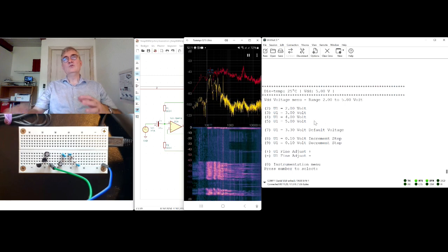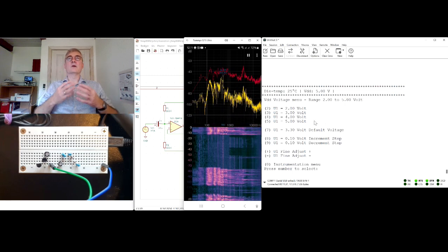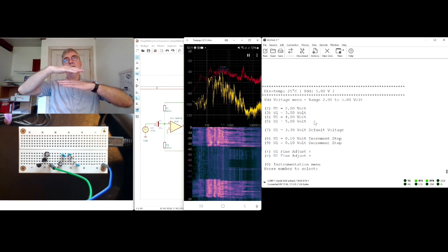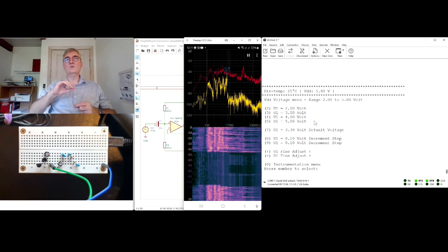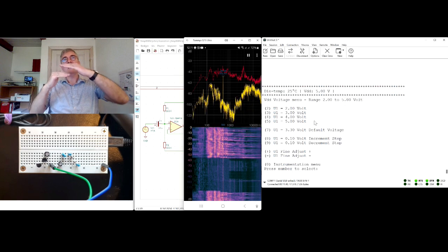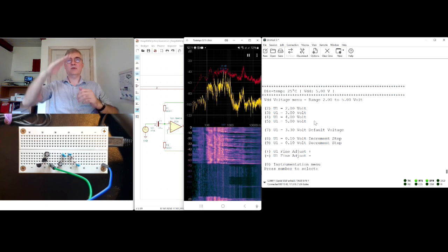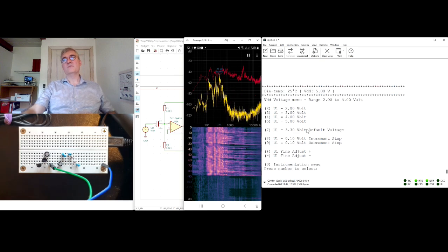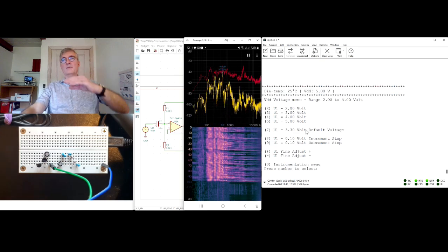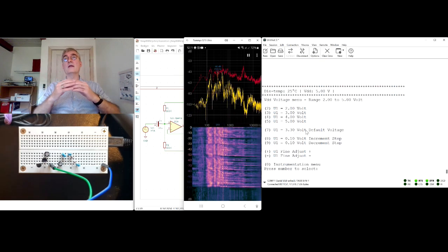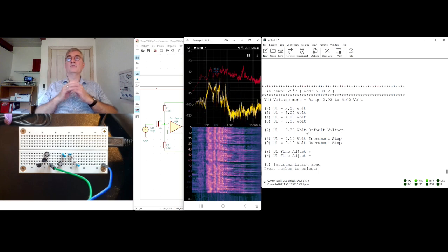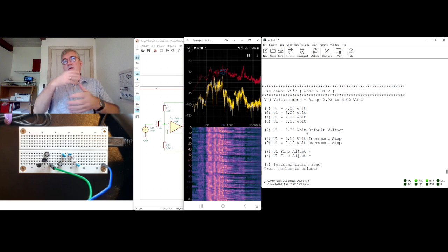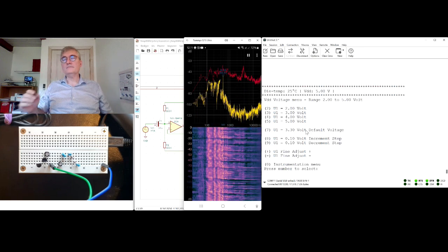And that's due to the fact that we start to get some clipping, because the power rail will be too narrow, and then the signal will start to saturate because it gets up to the top or down to the bottom here. So that's a good indicator that when we lower the power, and we can do lowering of the power from the firmware, the interface here, we also get this phenomenon called clipping.